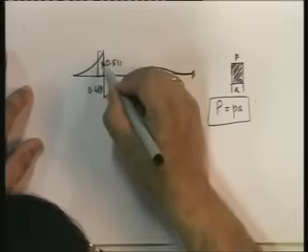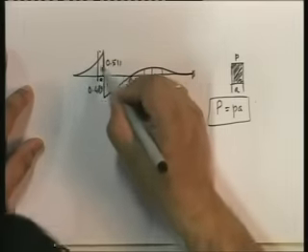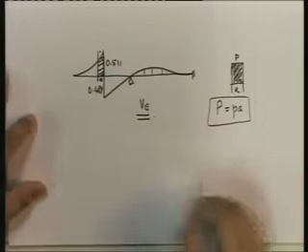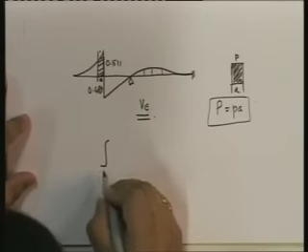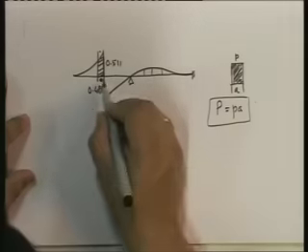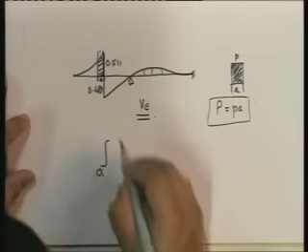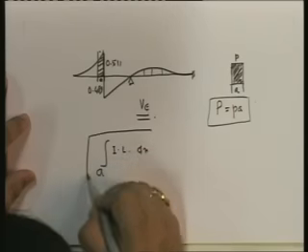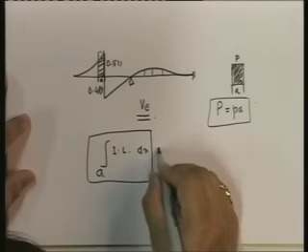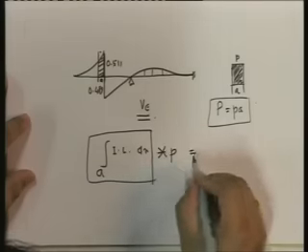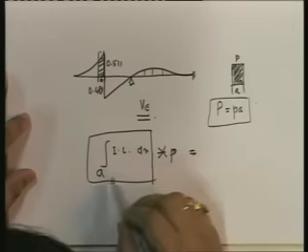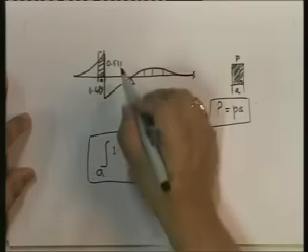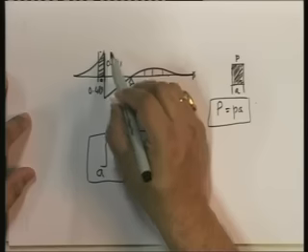So what we do is, we know this is A, and we find out the area under this curve. The area under the influence line over the distance A, when the load is placed at the maximum, over dx, multiplied by p, the pressure, gives me the pressure effect at this point.